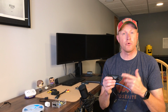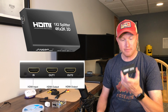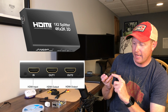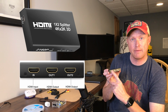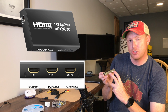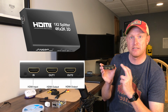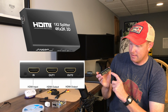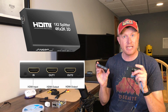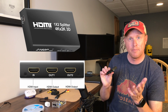Now since this capture card only has an input setting, we will need to also buy an HDMI splitter. So this has 3 ports on it. We have an HDMI in, so this will come from our cable box or Xbox, PlayStation, Roku, any HDMI device, and it has 2 outputs. One of these outputs is going to go directly to our TV, and that is the source that we're going to be watching. Now output number 2 is going to be going to the capture card using an HDMI cable. Now this device does need power to it, so you will need to have a USB power supply for it.